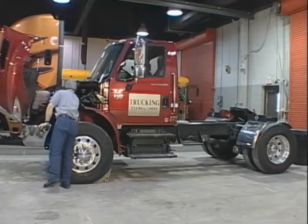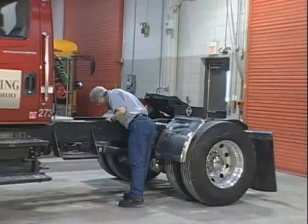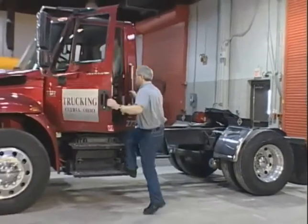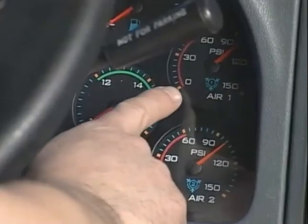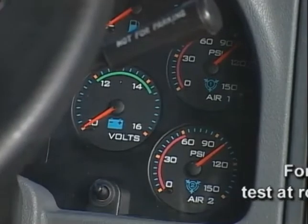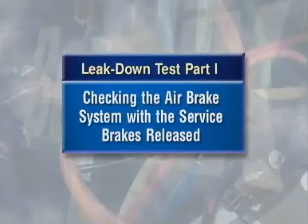Testing for air leakage can be quick and efficient with what's known as the vehicle leak-down test. Performing this two-phase test can help identify issues that affect compressor wear and tear and system service life. The results are read using the dash gauges, and for more accurate readings, it's best for the vehicle to be at room temperature. The first phase is checking the air brake system with the service brakes released.